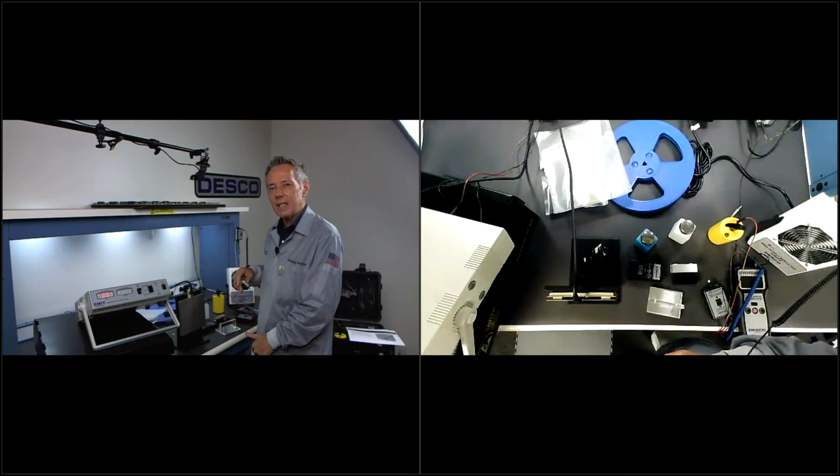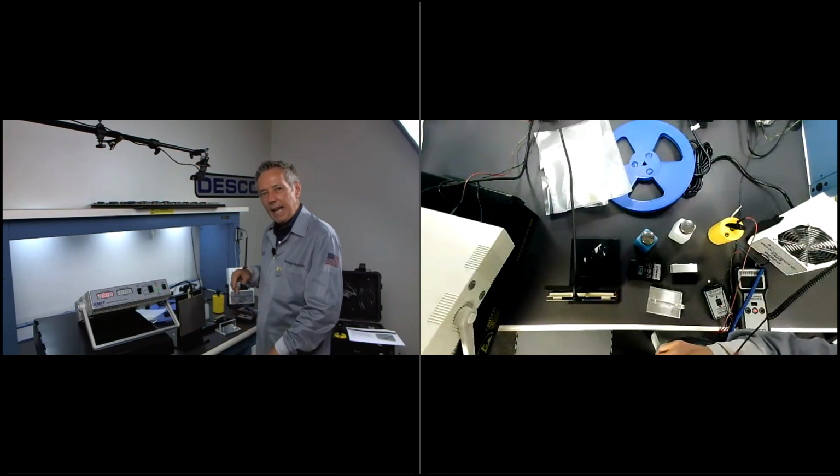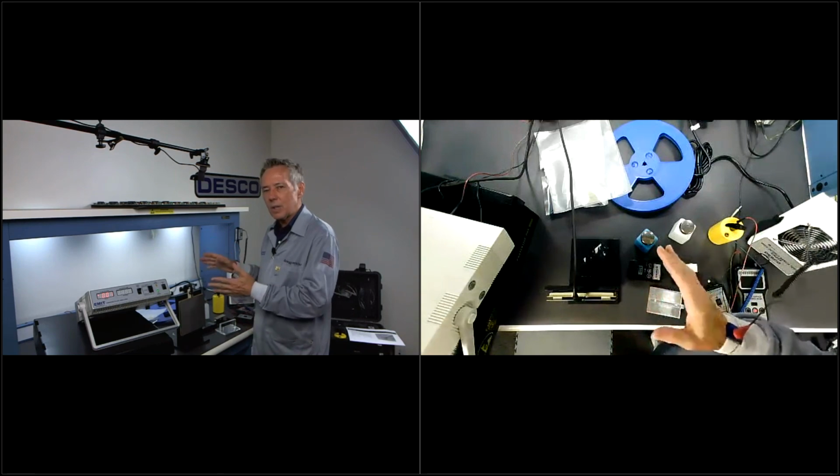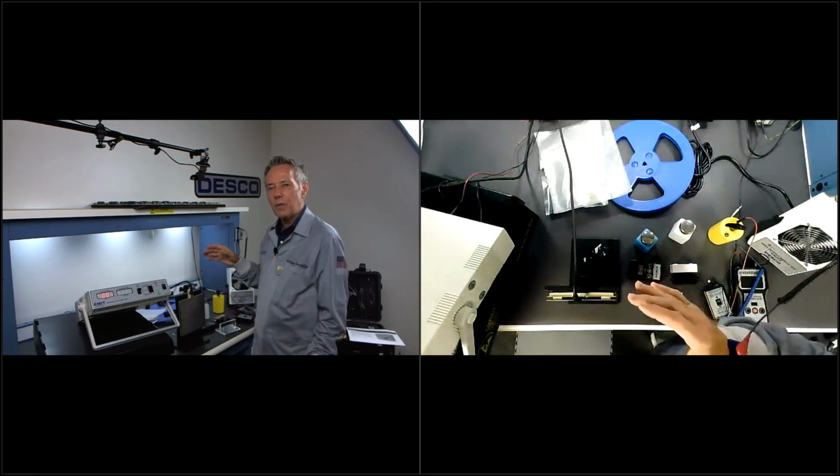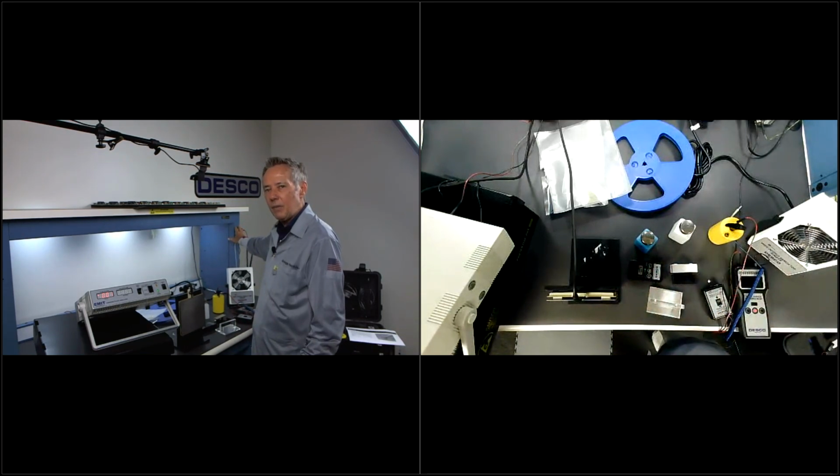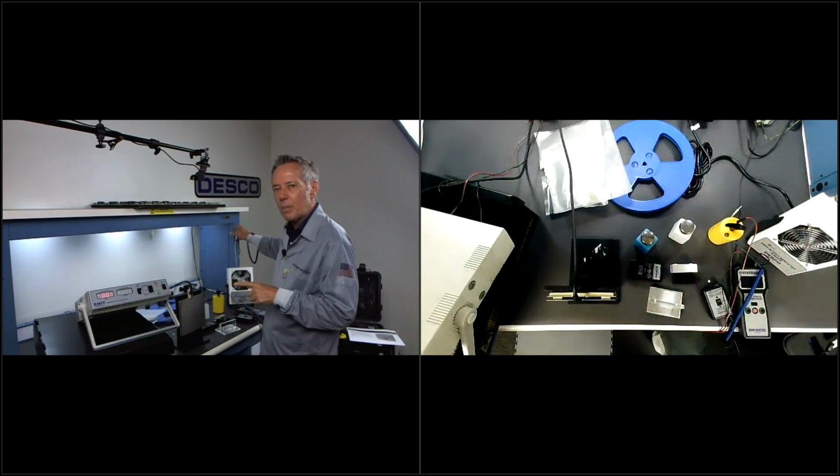That's because I'm wearing an ESD or a conductive foot grounder, and now I'm standing on my ESD mat. So there's a number of ways we can control static, whether it's through the wrist or through the feet, and ways that we can identify that we're in spec, and ways that we can make sure that our personnel are safe.